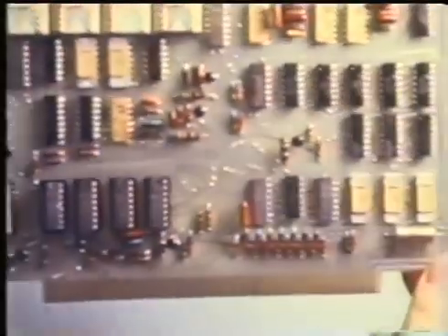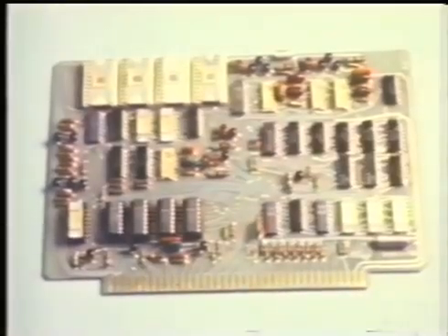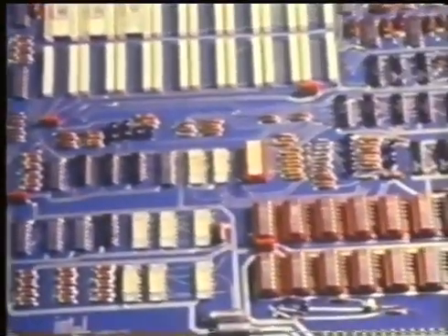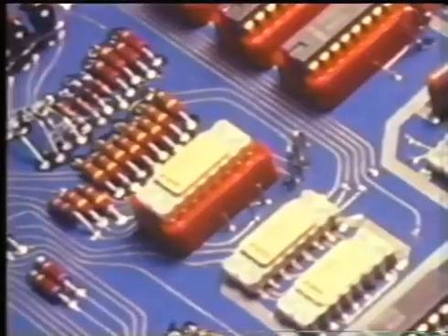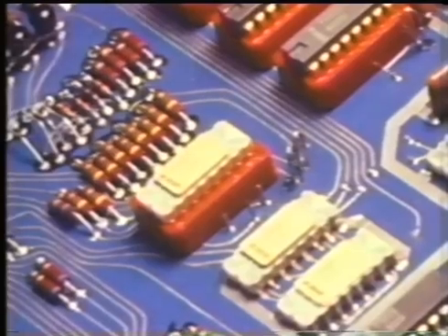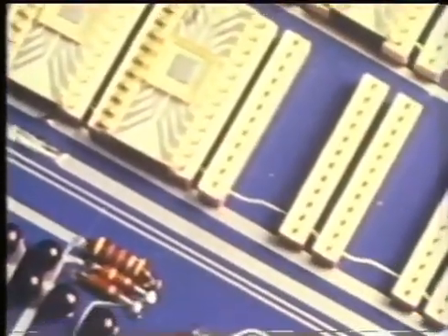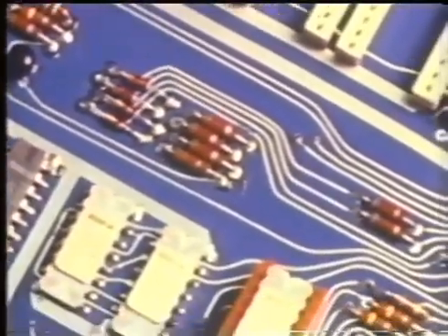To help you prototype systems, we can supply you with 2 special printed circuit boards, the SIM401 or SIM402. These boards contain a CPU, a bank of RAM memory, clock drivers, teletype interface, and a bank of 1701 PROMs, which simulate the functions of the 4001s and allow you to prove out your systems in your lab before committing to metal masked ROMs.